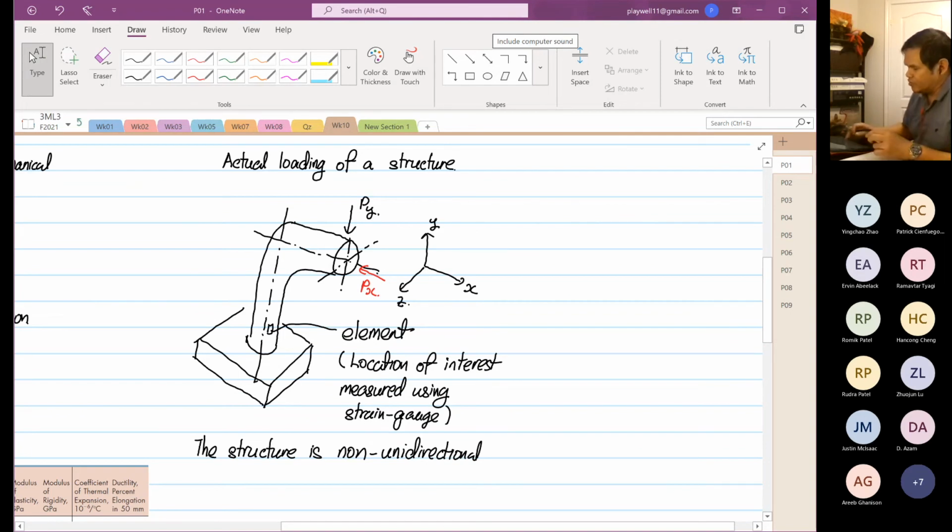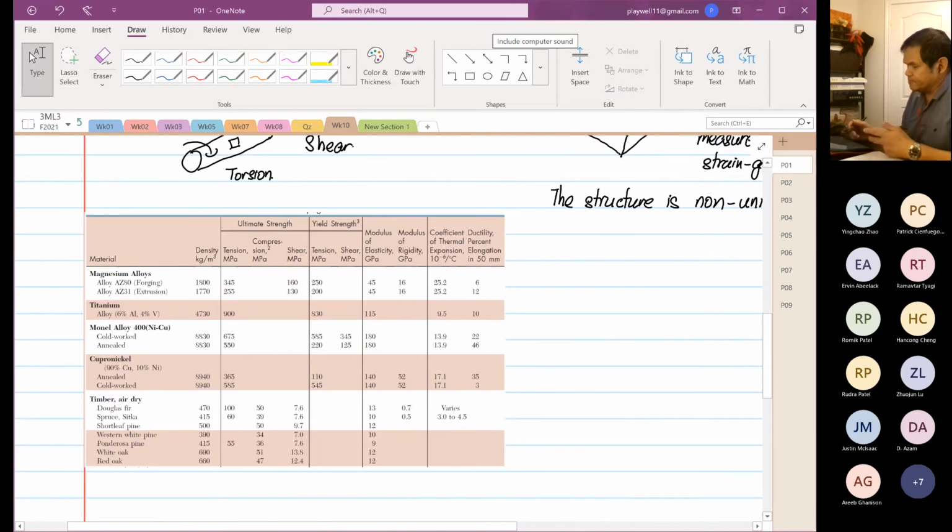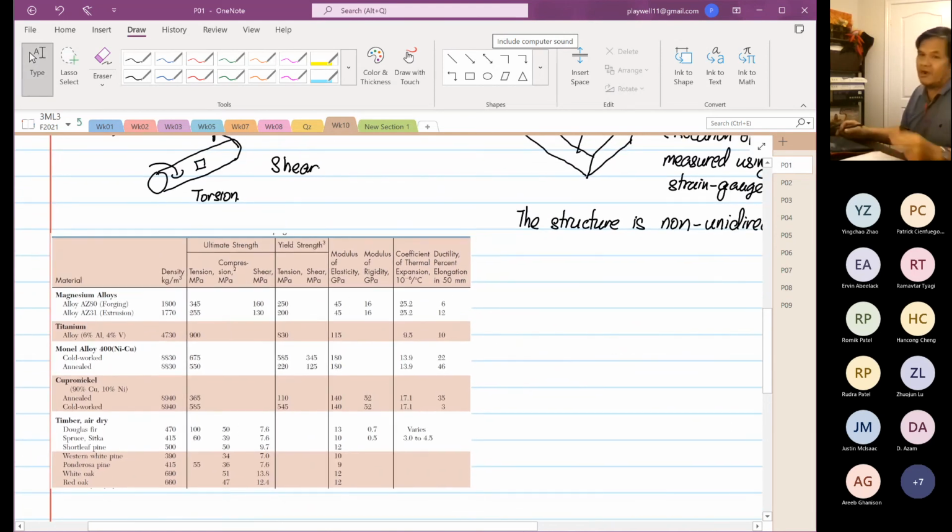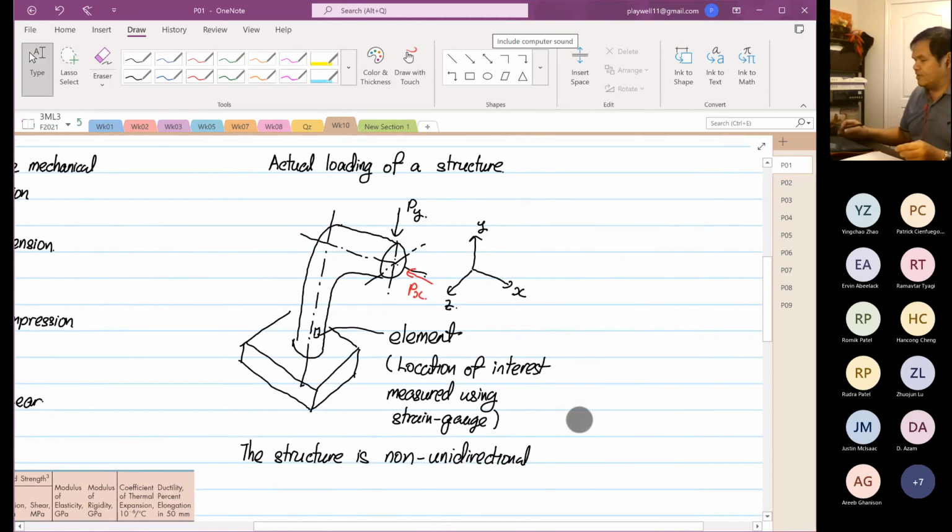So how are you going to use this data? Right? When I was working at Rolls-Royce, all I did is, okay, just take the one that has the highest stress component and just compare with the material property. That is wrong. Then we rely, okay, we are going to rely on finite element simulation for it to be more accurate. Good. Yeah, I was working for Rolls-Royce.